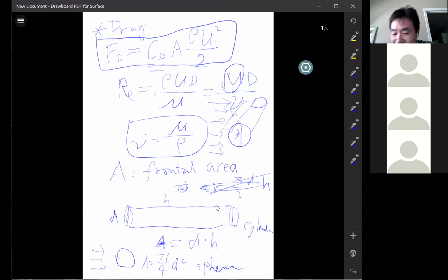Here, increasing the Reynolds number is just to increase the turbulence. How about we modify the surface to increase the turbulence? Scottish golfers actually found that when the ball gets old, very rough, no longer smooth, suddenly it flies further. We found that, and that leads to some thoughts. Some scientists 200-300 years ago said, what about making it even more rough? We put dimples on the ball.